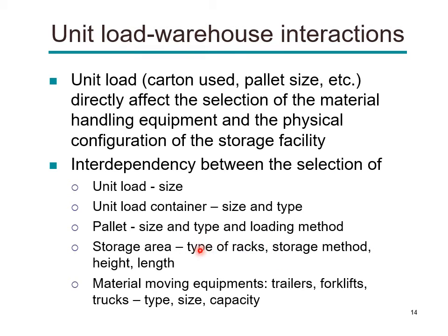We will consider these later on in the next chapter. And the storage method, the height and the length of the storage area, you have to decide on these. And for material moving equipment, you need to select trailers, forklifts, lifts, trucks, which one of these, and there are many alternative types of these. You need to decide on these, and also for each one you need to decide on the type, size, and the capacity of the moving equipment.